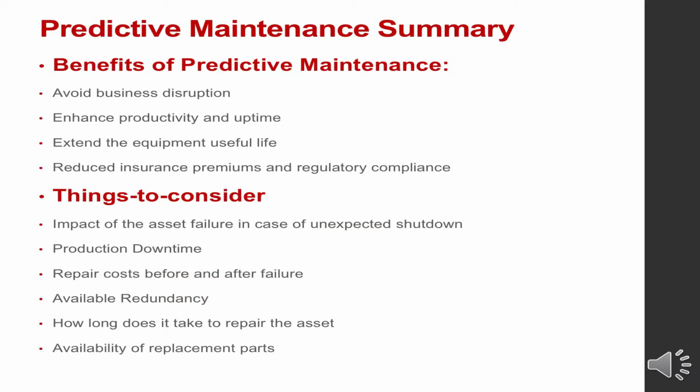For your critical infrastructure equipment like transformers, switchgear, or any other critical component of your power distribution equipment, you may want to use a predictive or a reliability-centered maintenance strategy. Why? Because you can understand the equipment health, you can plan for a shutdown, and also you can coordinate the logistics and resources required to perform the maintenance. Most importantly, you can definitely avoid an unplanned shutdown, which could significantly cost you.